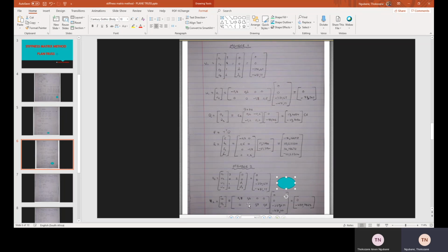And then we constructed this T. This is T times V. Then our T is cos, sine, 0, 0, 0, 0, cos. Then remember, on our first step for member 2, we calculated cos and sine. So we're using those cos and sine here. Then we're going to multiply our T times U and get our value here.